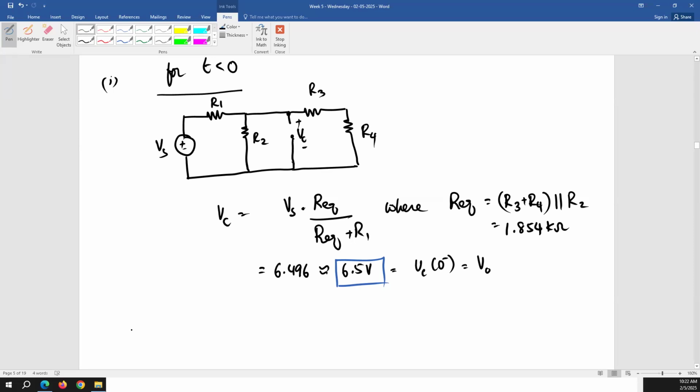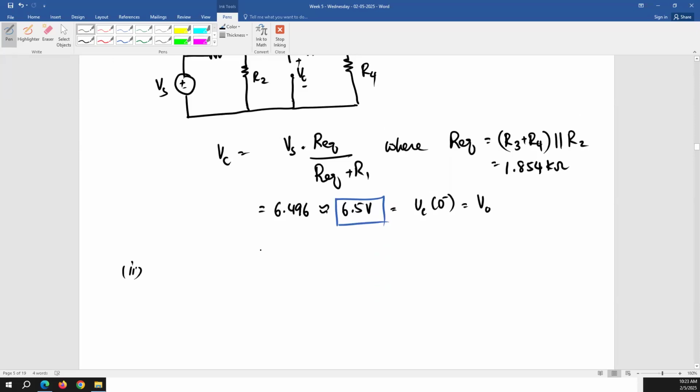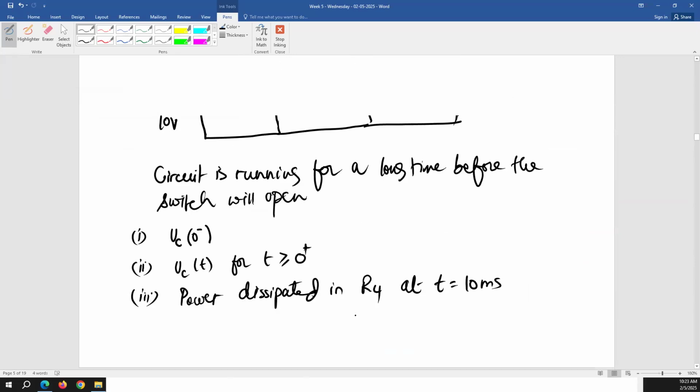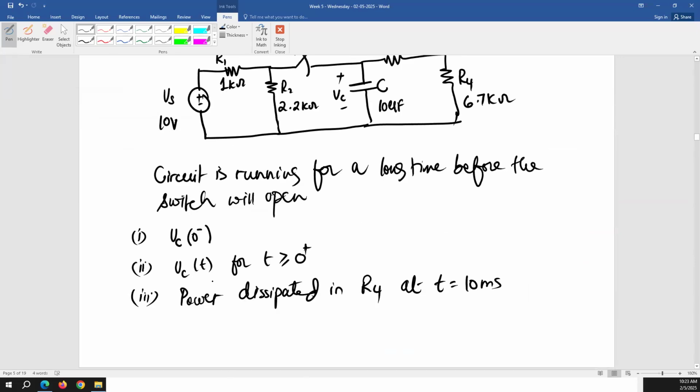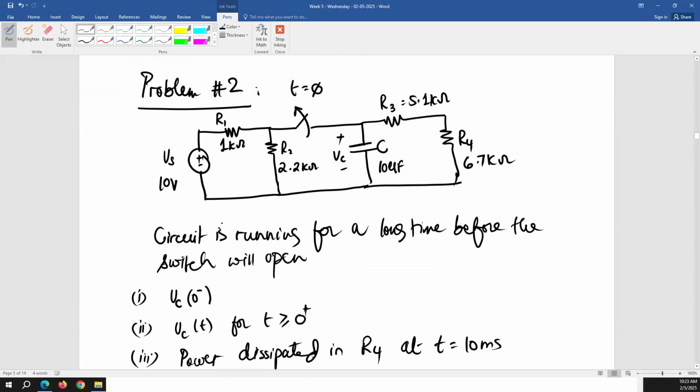So now the second part, where the circuit becomes source free. So the source opens up. In a source-free RC circuit, we are not concerned about the left side of the circuit anymore, because the question is asking us what is the value of the capacitor voltage at this time. Although when the source opens up, there is still this circuit here, and the source will still be supplying current here, we're not concerned about that. Our concern is now this circuit, C, R3, and R4.